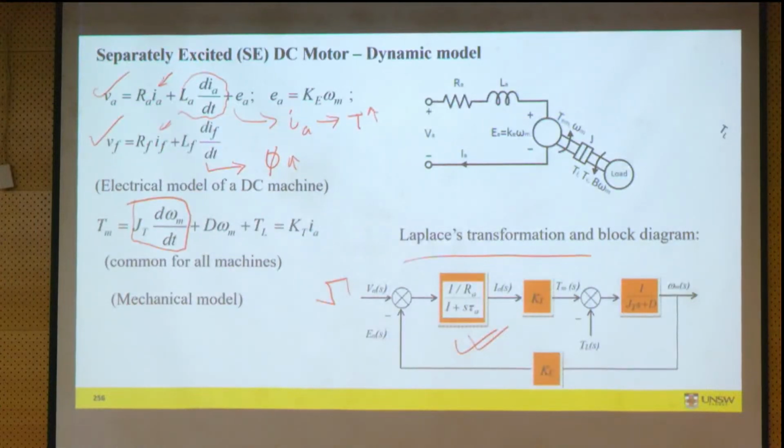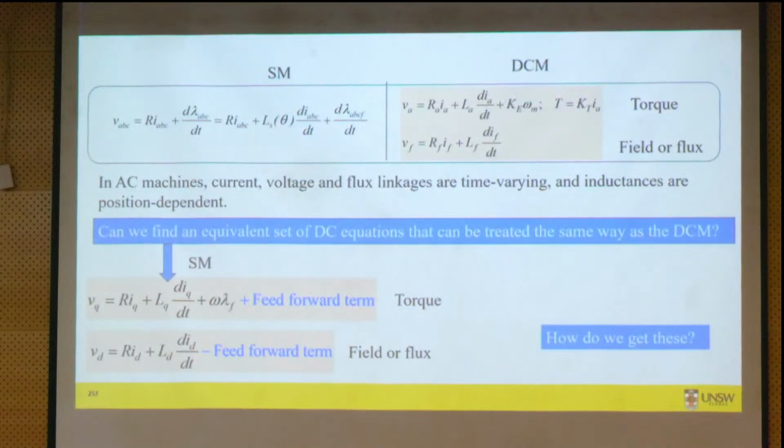If we can get a torque equation in which we can see how the torque and flux are decoupled from each other, that will also be useful. So that leads us to our dynamic DQ model equations, or the DQ dynamic model of PMSM. When we apply the transformation to our phase voltage equation, we can get the Vd and Vq voltages like these ones.